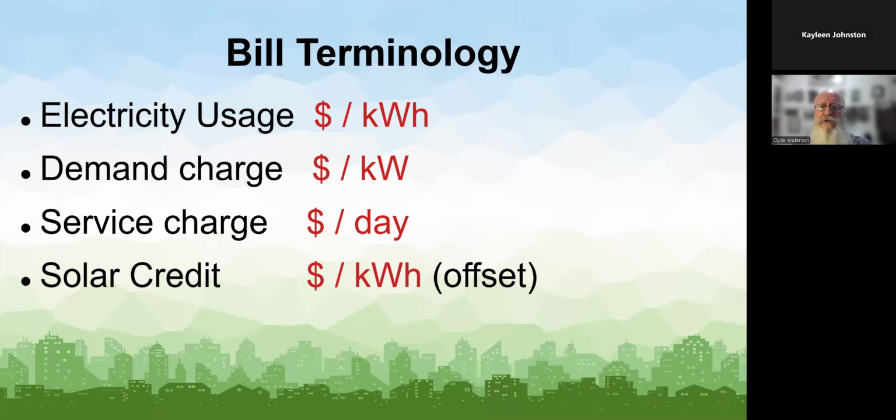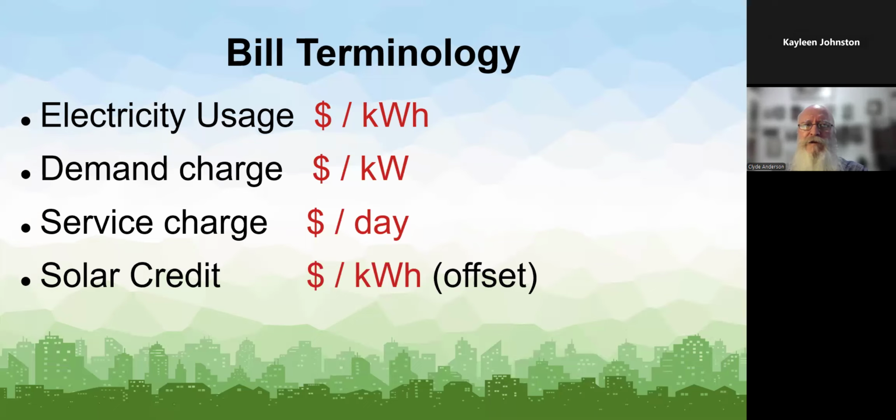And as a result, you can have a very high demand charge just because you have simultaneous appliances being used for that half hour. So to avoid the demand charge, reduce simultaneous use of large power use appliances, or stagger the use, or use timers is the best way to overcome that. I won't be talking about that anymore, but that's just how to reduce the demand charge.